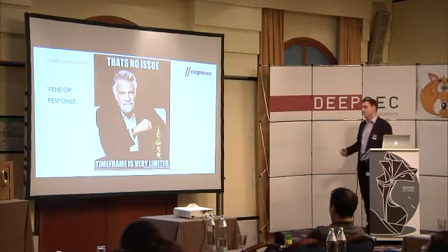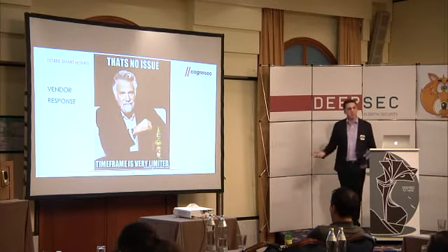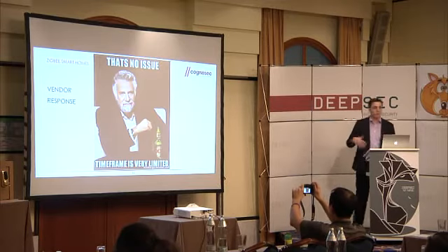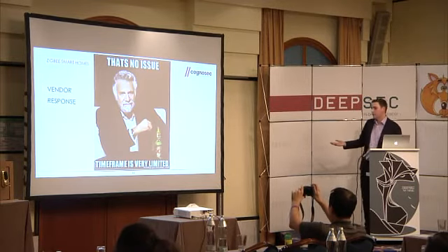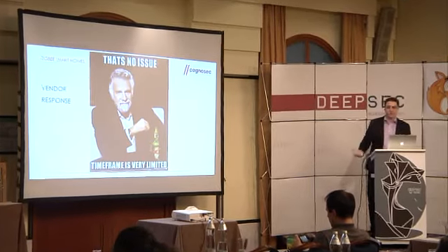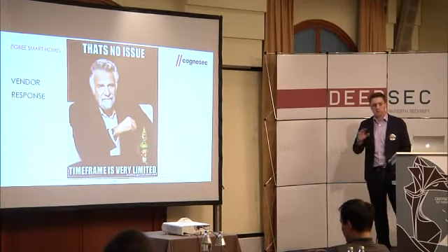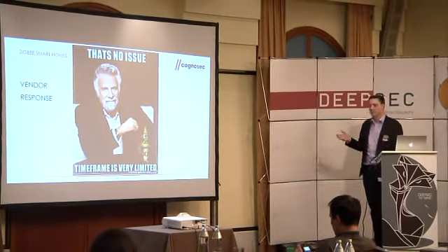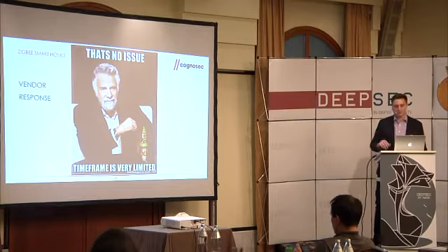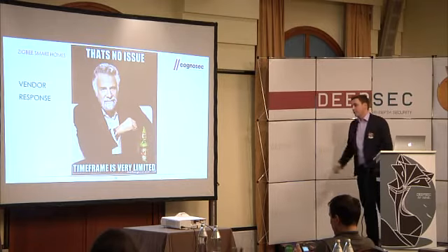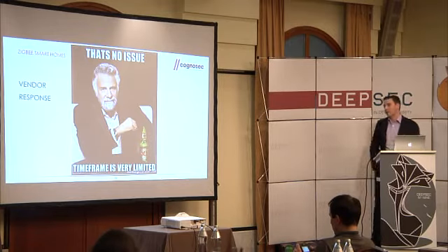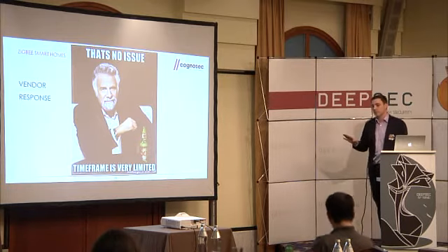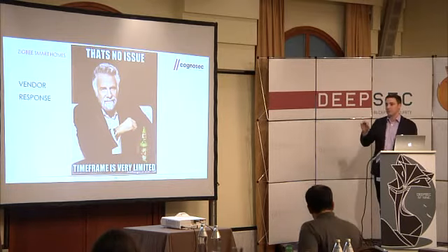So we took this and went to the vendors and also to the ZigBee Alliance and said, okay, this might be a problem because everybody is required to do this, and nobody tells the end user, be aware when you first initialize your pairing, make sure nobody is close around you doing this. But they said that's absolutely no problem because the time frame is very, very limited. That's true, the time frame is limited. You have to get exactly the right packets.